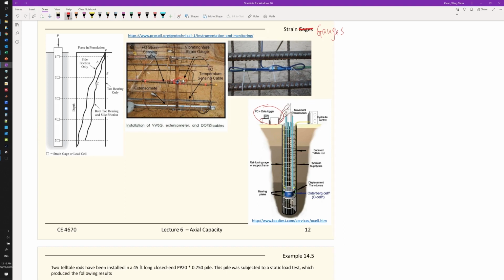And the challenge is not just placing the sensor in the ground, but having all the cables reaching deep down, going through all the adverse environments, like corrosive soils, or maybe salt water, and your cables need to endure all the travel and all the installation. Sometimes people also look at long-term performance. Maybe you want the sensor left in the ground for a long period of time, a couple of decades. And also very important, if you understand electrical engineering, the longer the cable, the more noise you will receive from the data logger, and then you need to process the data. So all of it is like an art, and this very good engineering work is rare for a typical project.